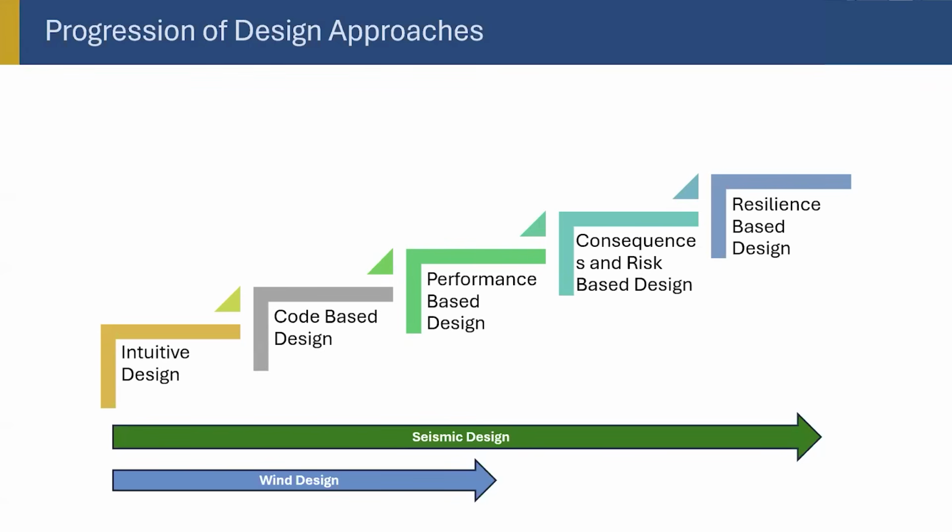People think it's a safe combination. It's not. And we will see later why not. Similarly, low wind and low earthquake, high wind also not a good combination. High wind and high earthquake is surprisingly not a bad combination. It looks bad, but it's not. So we will talk about these differences when we go to that part.